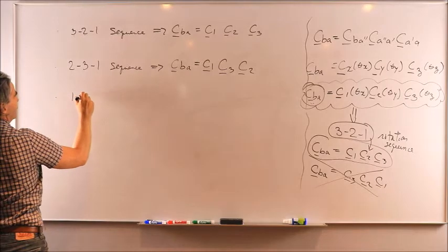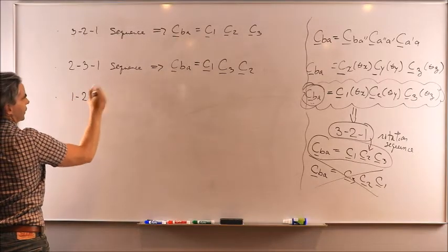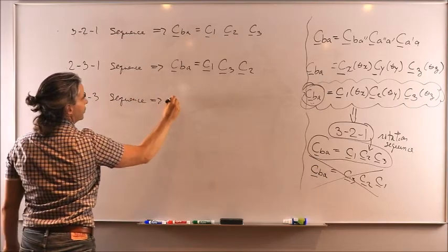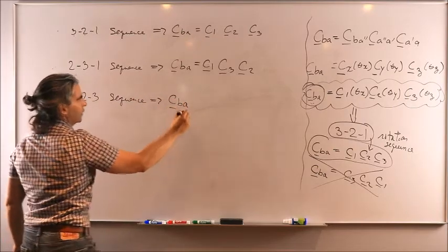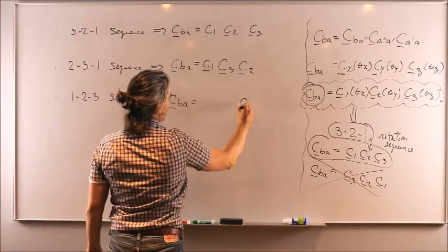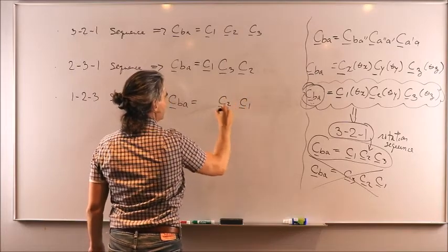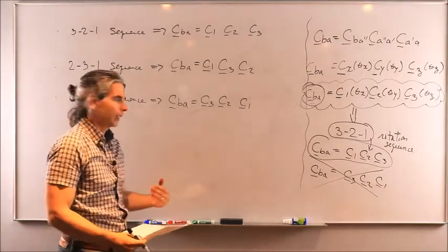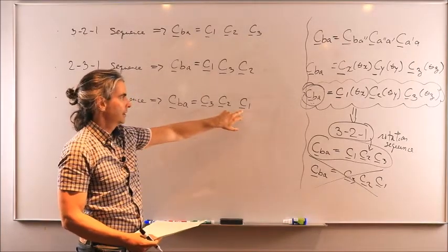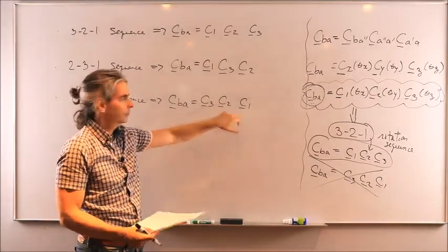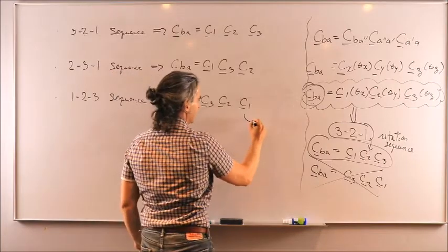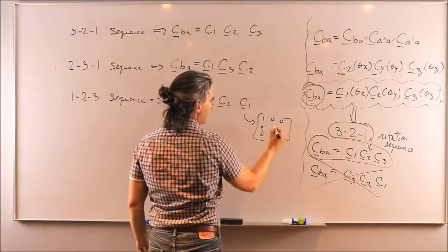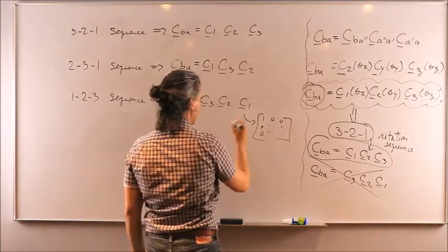1, 2, 3, let's say. Sequence would translate into a rotation matrix of 1, 2, 3, like that. Meaning that you go back to the lecture notes, pull out what Cx or Cy is equal to, remembering that this is the 3 by 3 with the 1 here, the zeros over here, and cosine of the angle of rotation.